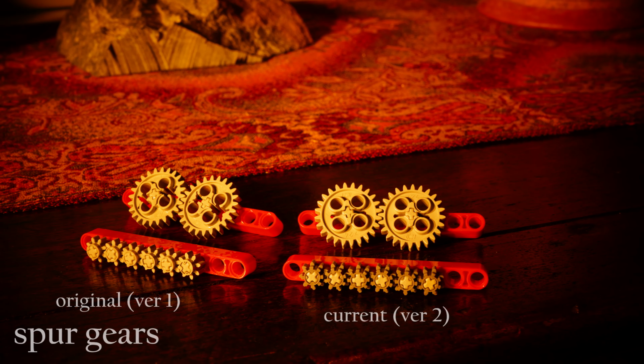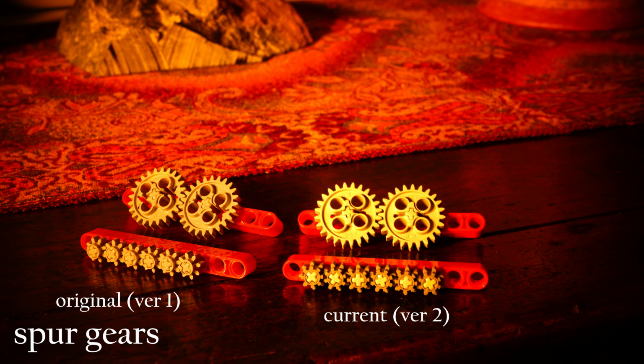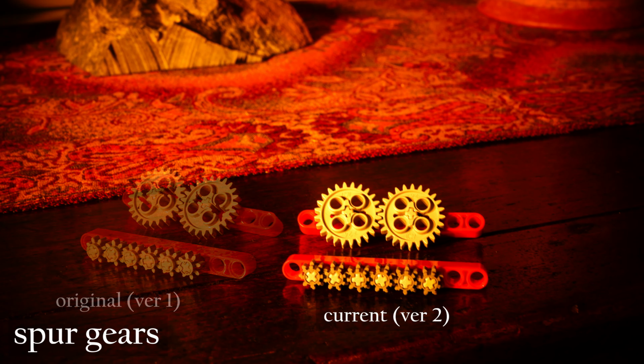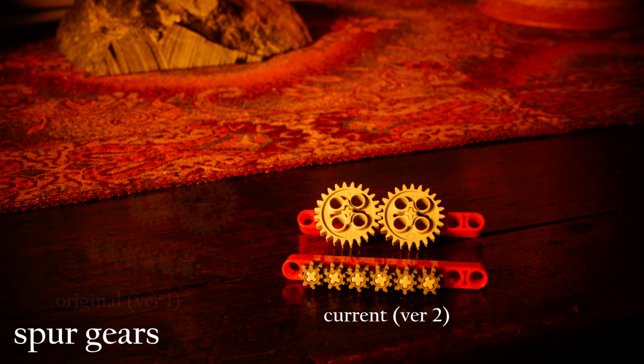LEGO spur gears are the OG LEGO gears, dating back to the late 1970s. Both the 8-tooth and 24-tooth spur gears have been improved over the years, with the current version of each pictured to the right. Note that each 24-tooth gear covers 3 holes, or studs, and each 8-tooth gear covers 1 hole, or stud. Each LEGO stud represents a distance of 8 millimeters, so a LEGO gear's diameter in millimeters will always equal the number of teeth.